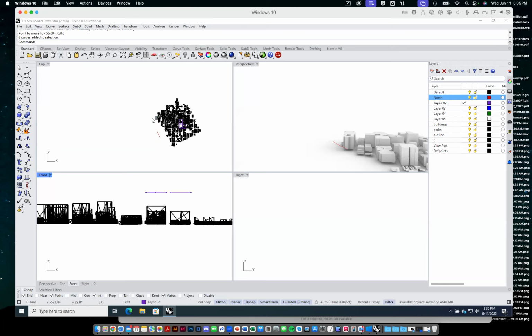So this is a nice tool that Rhino has. The other thing I'm going to do is lock this north arrow. So this is telling us where true north is, right? And reminding us that when it comes time to monitor the sun, we either have to rotate the sun position to where true north is, or we need to rotate our model back, right? So just so you remember that, that red line is not just something stray. That's the north-south axis for the cardinal directions on the compass.